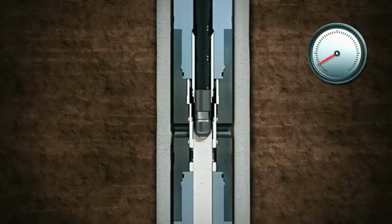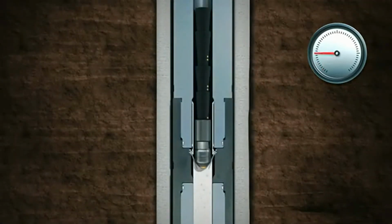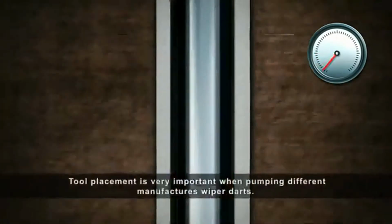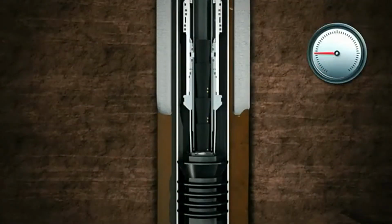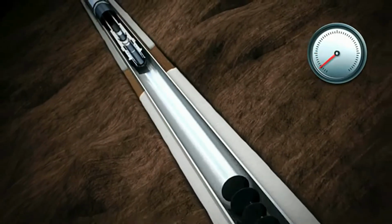When the wiper dart hits the seat in the Blackhawk diverter, you will see an increase in surface pressure. Pumping will continue until the dart hits the seat in the Blackhawk diverter test device. Again, you will see an increase in surface pressure. Tool placement is very important when pumping different manufacturers' wiper darts. Pumping continues until the liner or subsea casing wiper plug assembly is launched, causing another pressure spike.